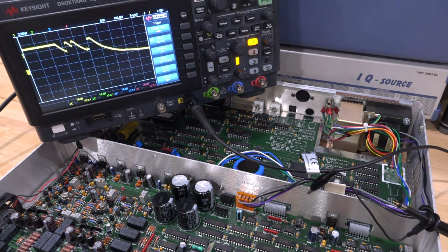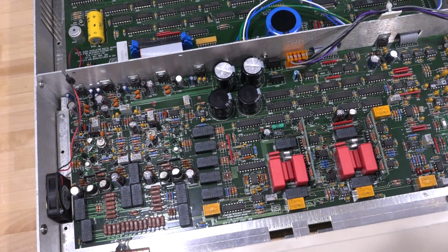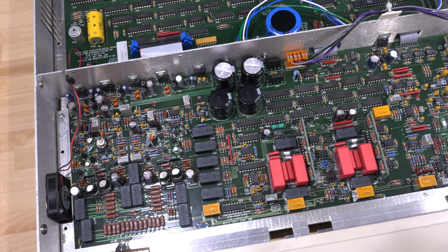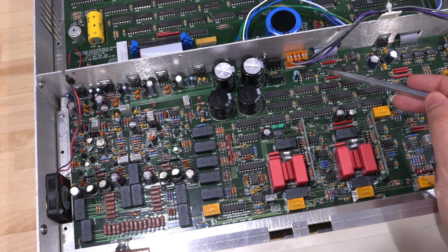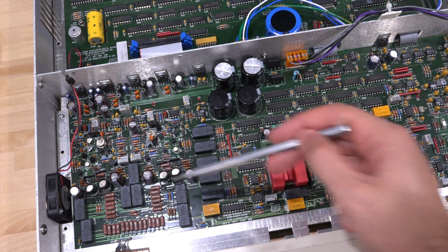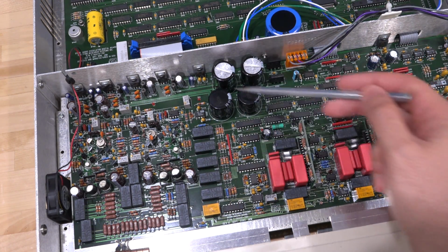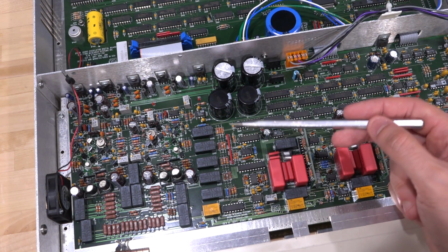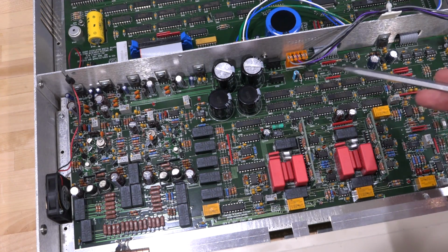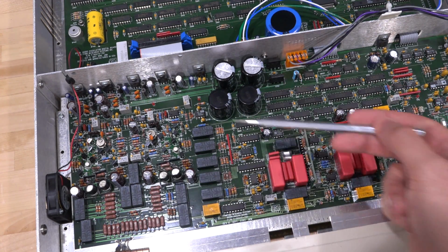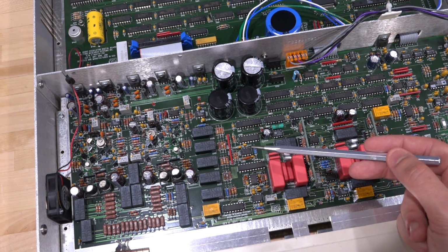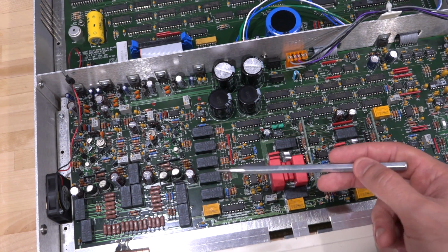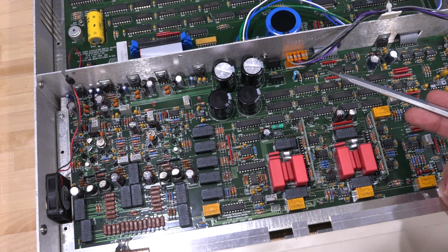I suggest we remove that optoisolator and try it out. So I removed this. It wasn't easy, and one of the pads came off. So we're going to have to figure out how to repair that, and we're going to measure that optoisolator in just a second. But I did kind of smell something around here when it was running, and I did check, and a few of these resistors are sitting at 150 degrees Celsius. And I worry that might be because without this configuration, there might have been some conflict of registers and turning things on and off that shouldn't be on, and maybe they are burning out because of that. I hope there's no other damage, but anyway, there's nothing we can do. We have to do it one step at a time.